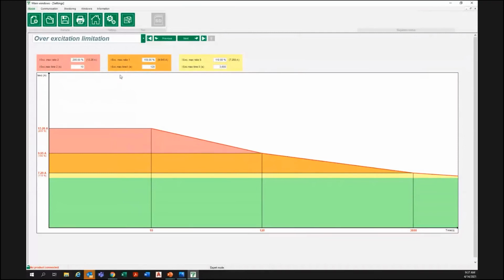And we will want to use this setting because excess current in the exciter can cause overheating. It can also cause an over voltage or over current in the generator itself. So we don't want to overexcite the generator.